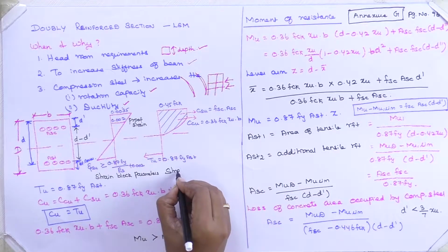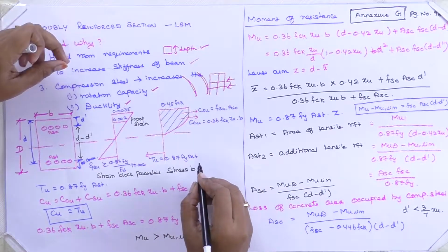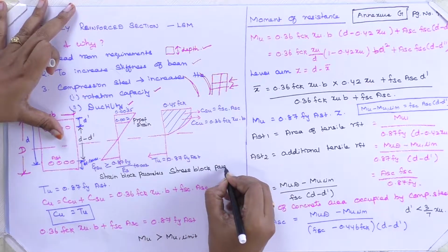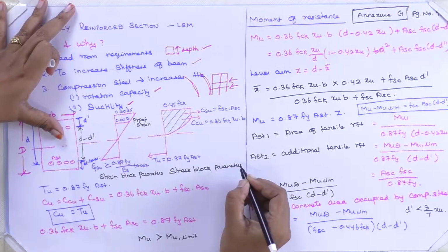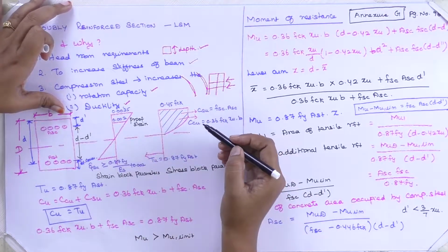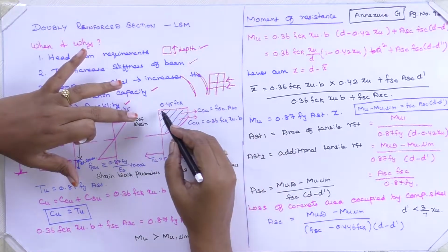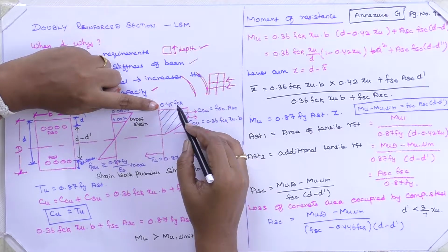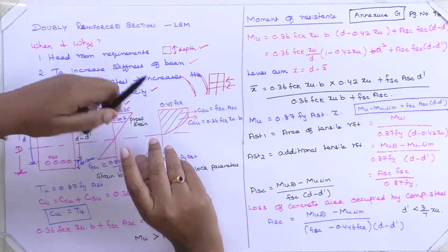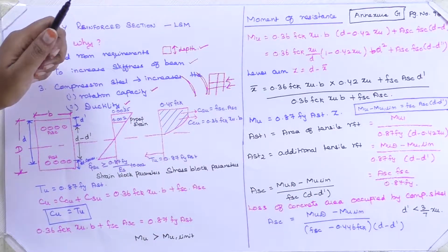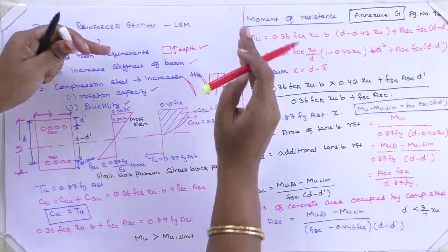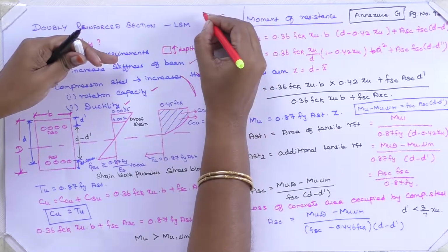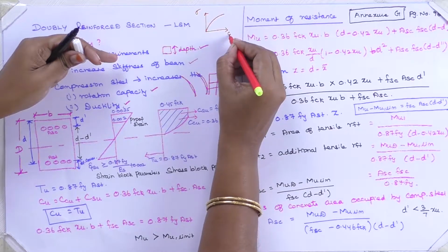Okay, now we'll see the stress block. Now we'll see about the stress block parameters. We all know the stress block parameters for concrete. The maximum design stress is 0.45 FCK, where I have got these values from my curve, this is my stress, this is my strain.